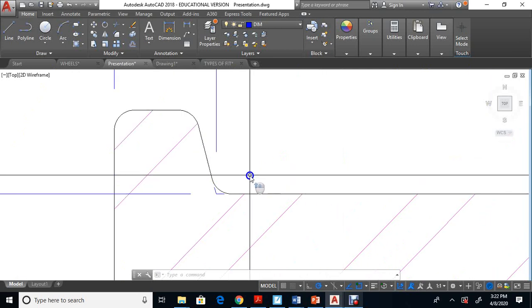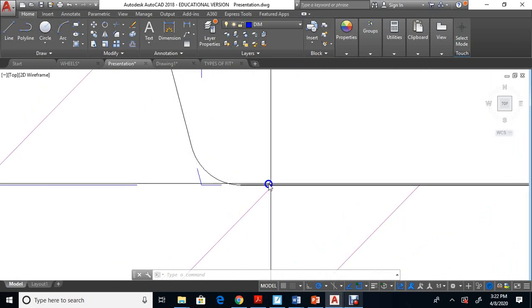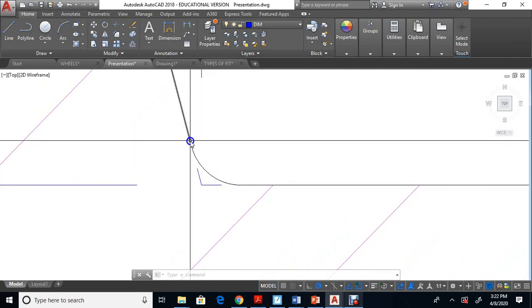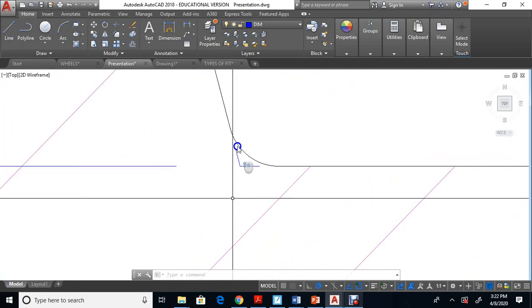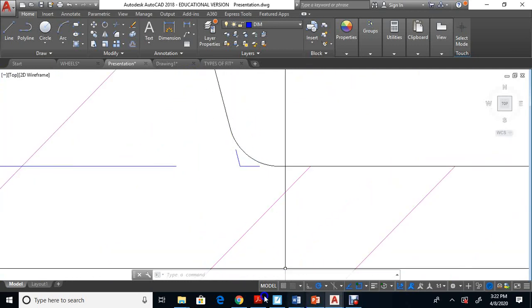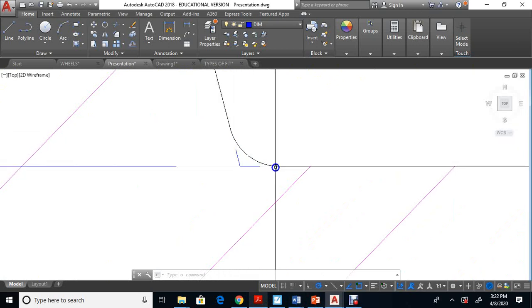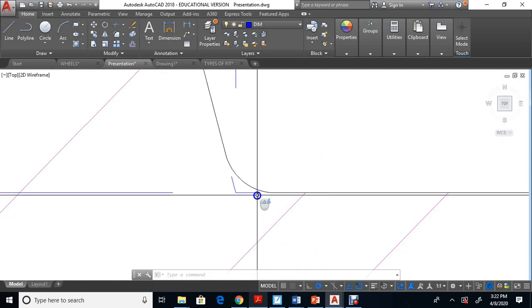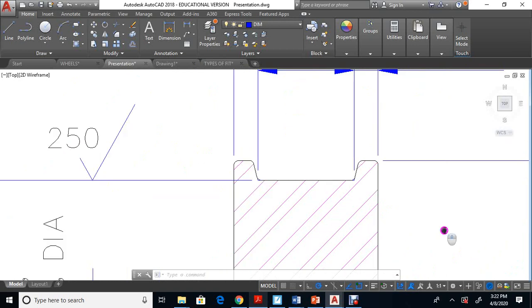In here, you've got 5 and you've got this 3 1/2 inch diameter. Interestingly, I made a straight line come down here and a line, and then I curved it. This dimension actually goes before you curve it. So this 5 here, if I zoom in really closely, it's to where this line meets and that line meets. So I created this little piece here, without touching, so I can dimension this. It's very hard to see when you zoom out.